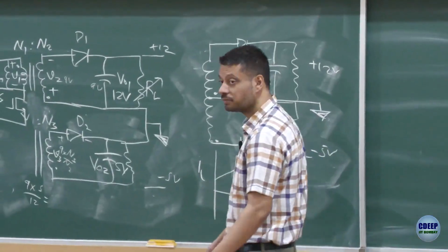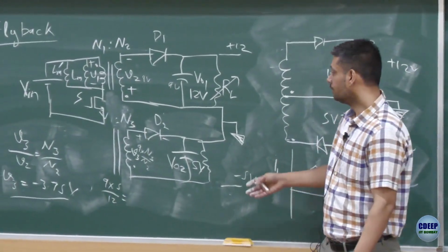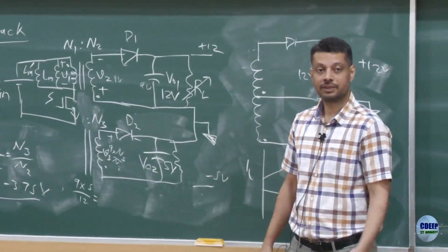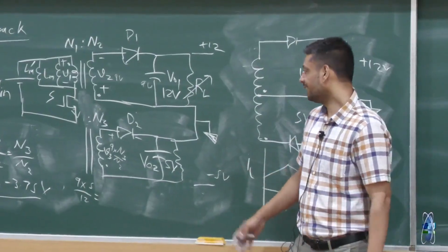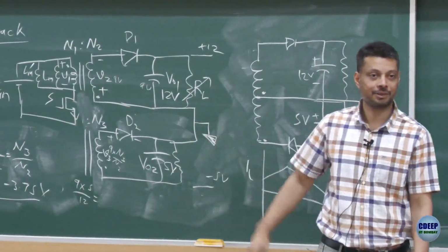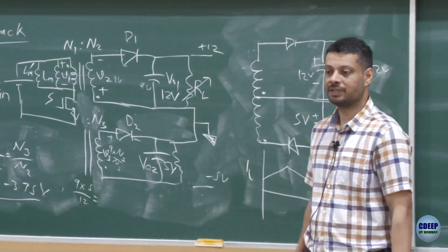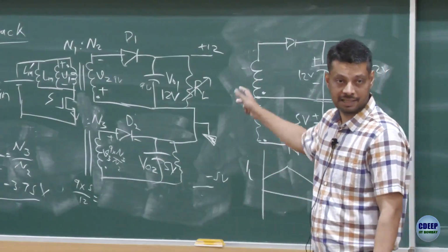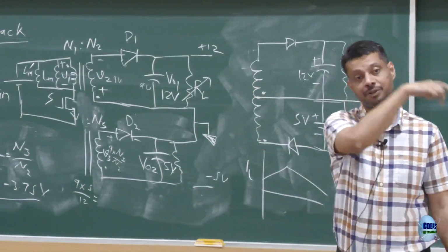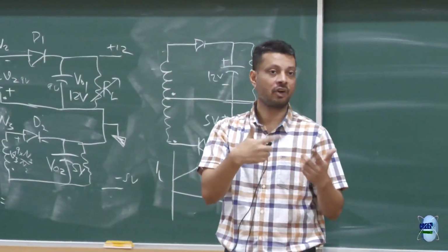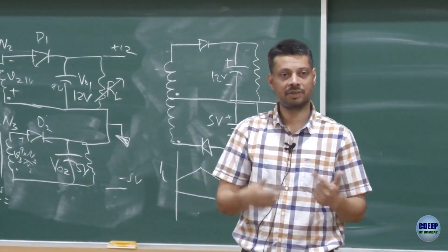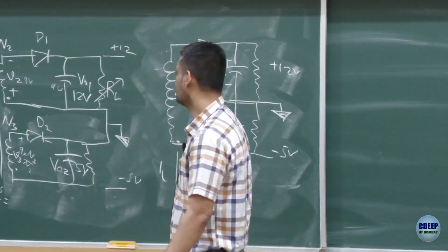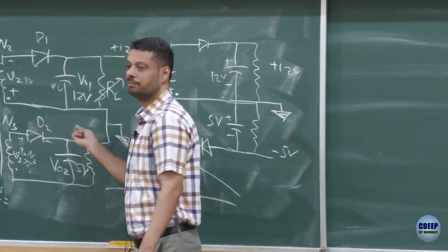Yeah, but here first of all you are getting an opportunity to get 2 voltages, which was not even there in the buck converter, right? So firstly you should be thankful to this circuit. Nobody is perfect, right? So this one is also not perfect, but still does a better job than just a buck converter. You are absolutely correct that if one of the voltages drops, it would also have an impact on the other voltage. There is a term for it, we call it cross regulation. Something we can see later on; if you want, you can search it. Cross regulation, right.